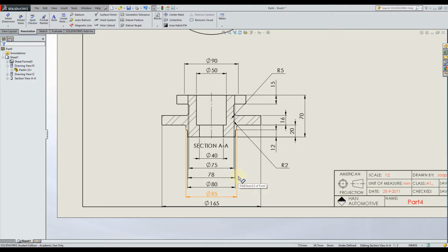So it still requires some manual work, but it saves you a lot of time and usually prevents the user from missing a dimension. Now I should say, when you're using relations on some kind of pattern, not all the dimensions will be importable. So this isn't some flawless method. It still requires you to double, triple check all the dimensions to see if they're all there, to make sure they're positioned properly, and to make sure they're actually useful for production. Because not all dimensions you use in your sketch are actually useful in the actual production environment. So keep that in mind.